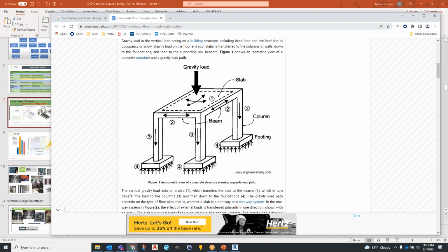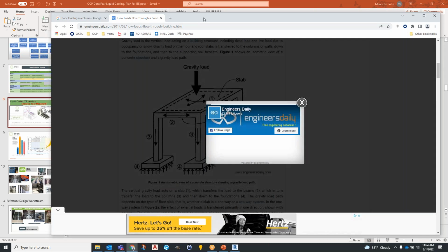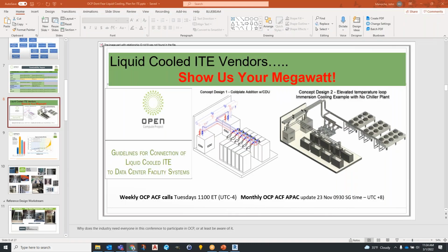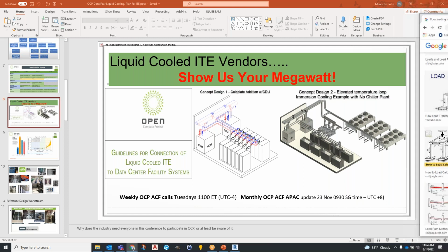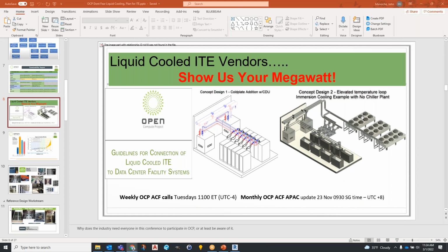And the other thing is, your number 325 might be very good for a single phase. In fact, the fluid is lighter, and you don't have the pressure problem where you have to contain it. You don't have a GWP problem. But if you're going to have a two-phase immersion solution, you of necessity have a much sturdier tank because you have to contain it and leak proof it, and then you're going to find that the numbers readily exceed those of single phase. So yeah, you can provide very detailed guidelines, but then it becomes almost halfway engineering there.